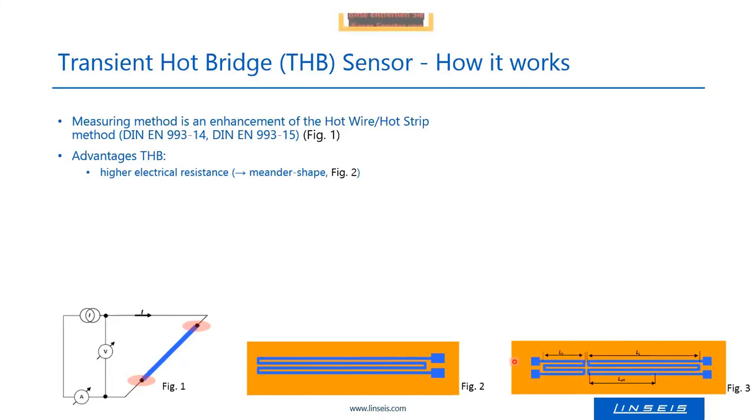And when we subtract this smaller part from the part on the right-hand side of the sensor, then we get fully rid of what is happening in that part. And the effective length where we measure with that hot wire is only in the middle, along this effective length without heat losses. And this is a big step forward, which brings the uncertainty down by a couple of percent.